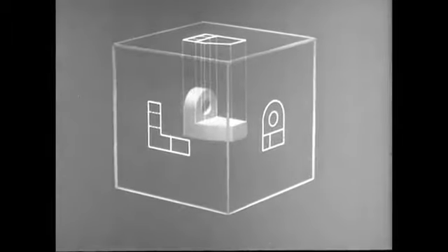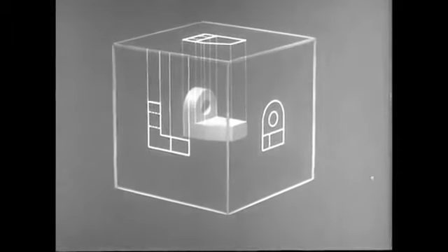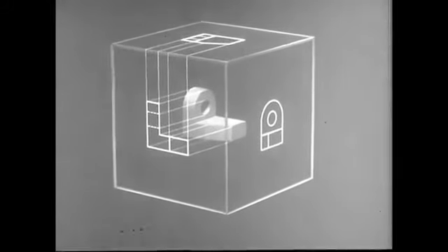You know you will need the top, front, and right side views. But first, study the planes of projection to see how these views must be placed. Notice that projection lines creating the top view can in turn be projected on the front plane. That is, they have their images on the front plane. Projection lines creating the front view have their images on the top plane.